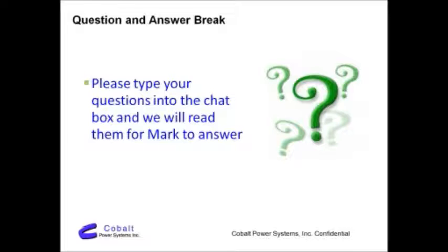Okay, I'm going to allow this one last question. If you are off the grid, what kind of battery backup is best? Now, when you say off the grid, you mean no grid connection whatsoever. So if you're off the grid, by definition, that means your batteries are being exercised a lot. Every day, the battery will be charged up. Every night, it will be discharged. Not all the way, but some percentage. And that requires a different battery chemistry than a standby application, which is sort of the suburban environment. And so you want a flooded lead acid or lead calcium battery if you're off grid.